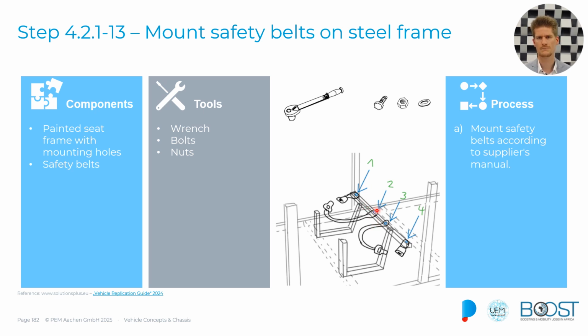And just calculate how many people you want to have here. We are currently thinking about 2 people, but probably 3 would be also right in one row. And then you position the seatbelt attachment points, drill a hole through the profile, and then with bolts, nuts, and washers, you secure them and bolt them to the profile, and the lock is done in a similar way.